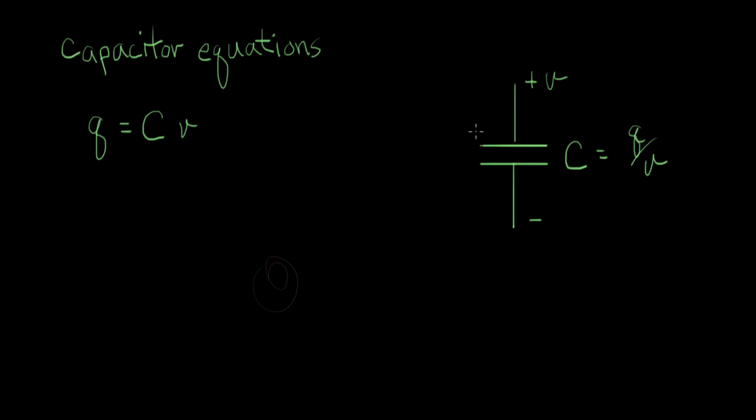So what we mean by stored charge is if a current flows into this capacitor, it can leave some excess charge on the top. I'll just mark that with plus signs, and there'll be a corresponding set of minus charges on the other plate of the capacitor. This collection of excess charge will be Q plus, and this down here will be Q minus. And they're going to be the same value. When the capacitor is in this state, we say it's storing this much charge. And they're going to be the same with opposite signs. So that's what it means for a capacitor to store charge.